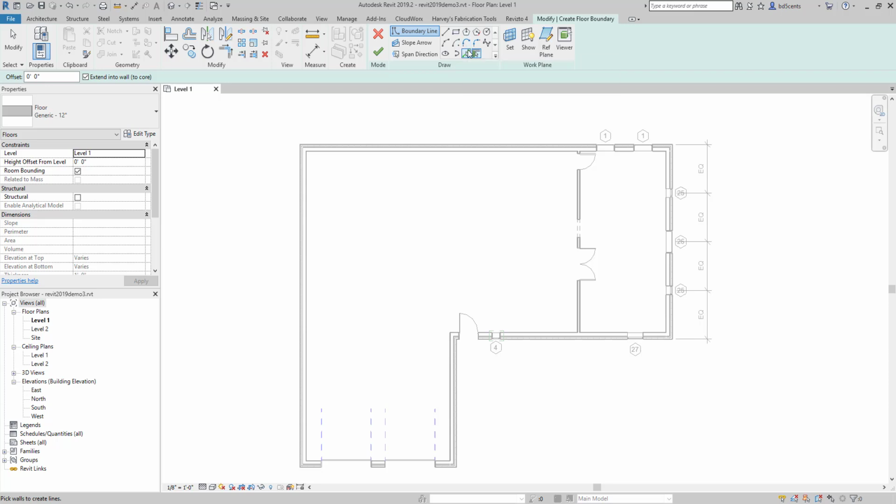We're then going to pick walls, the icon in the draw tools area, which is right here. So pick walls. Double lines are the span direction as we click these walls, and you should see magenta lines as you pick them. So I'm going to go ahead and click, and you'll notice that it's selecting that exterior core wall.